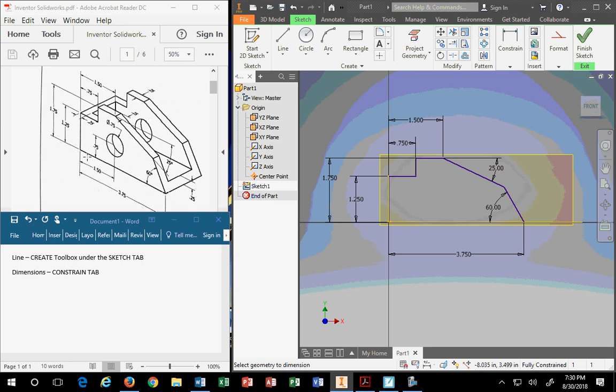Are you with me on that? So you fix all those dimensions to reflect what the customer drew. Because are you going to remember that when you do the detail drawing for this part? No, you're not. I guarantee you. Remember, whatever dimensions you put in this model, they will directly translate to your detail drawing. And that is the number one complaint companies have. The detail drawings just don't look right. Why? They're putting in dimensions that don't even belong there.